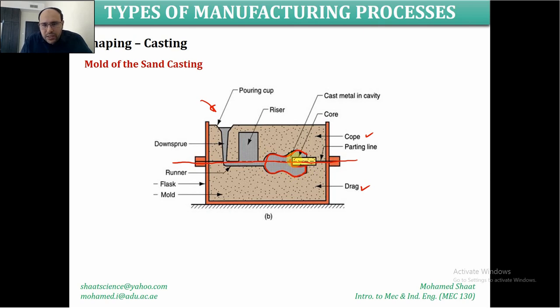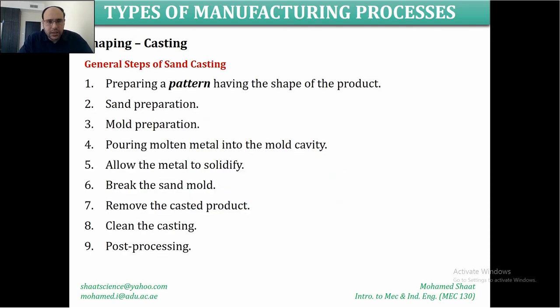All these things and the product, which should have a hole, and these extra things are just channels known as the gating system that allow for the easy transfer of the liquid to fill the mold cavity. Make sense? This is the procedure that I showed you in the video.